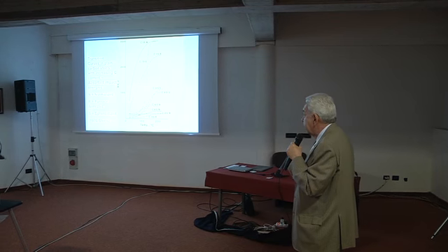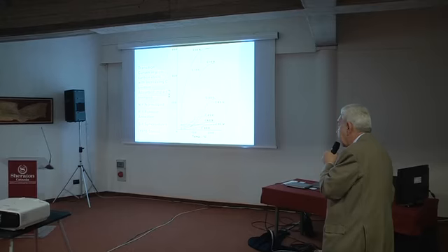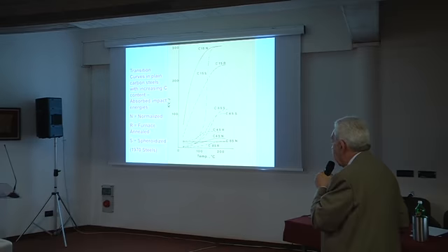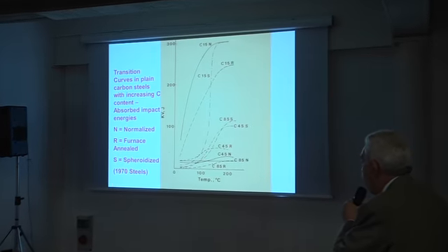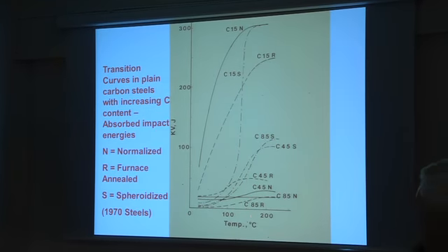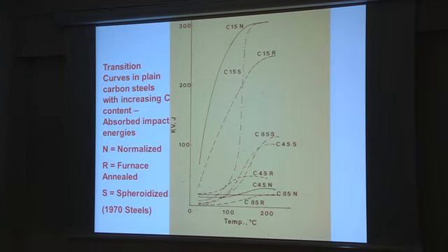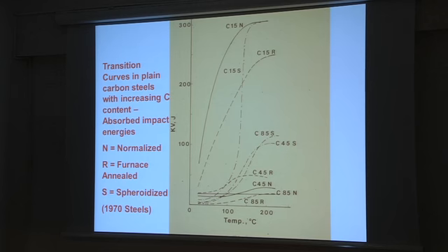At high temperature, they reach the maximum absorbed energy. And when we go to higher carbon content, no matter the temperature, the absorbed energy is always low. But they may fail in a ductile or in a brittle mode.